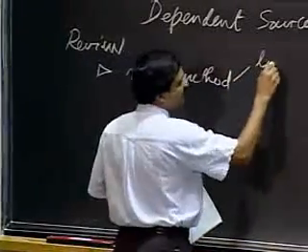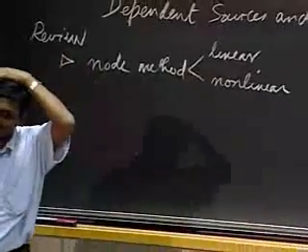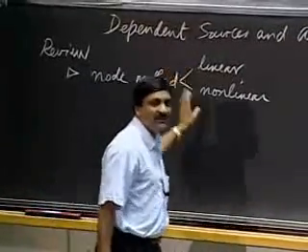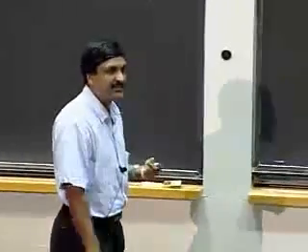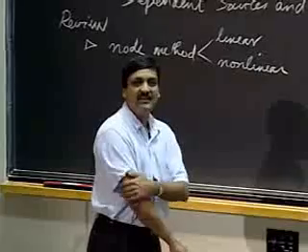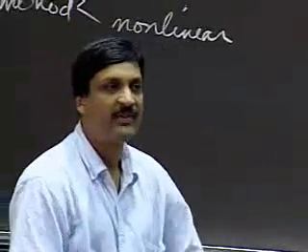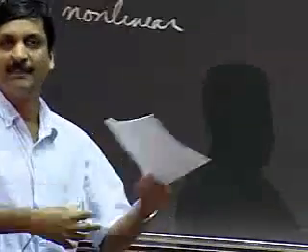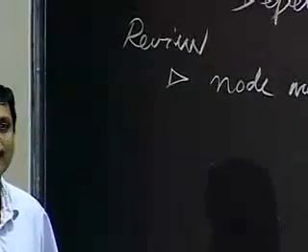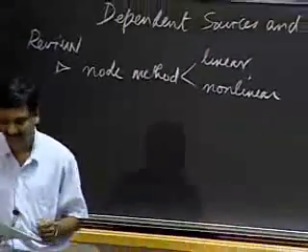And this will work both for linear circuits and nonlinear circuits, okay? So if you see a problem or if you see a situation in real life that requires analysis, then as a first step, you should try to think of whether you can apply some of the key intuitive shortcut methods. Superposition, one of my favorites, the Thevenin method, Norton method, or the method that involves composition, that is very quickly analyzing circuits that have resistors in series and parallel. Okay? So if you can apply one of these quick intuitive shortcut methods, go do so. All right? If you can't, then usually you can resort to the node method, irrespective of whether the circuit is linear or nonlinear.